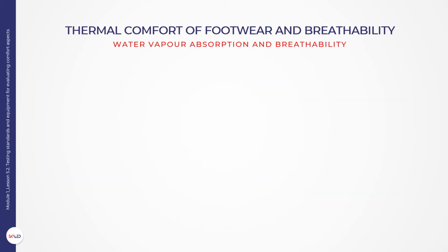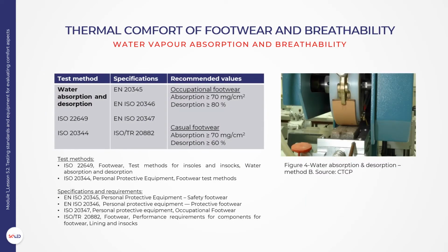Water absorption and desorption. The water absorption is the gain in mass per unit area of the test piece due to water absorption during one or more specified periods of time, and the water desorption is a percentage loss in mass of the test piece, expressed in terms of mass and water absorbed.